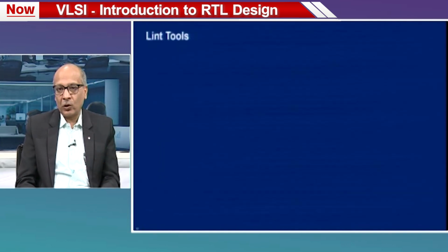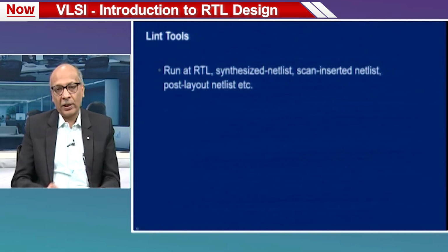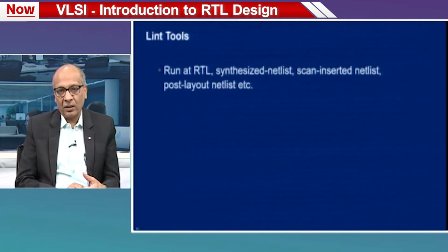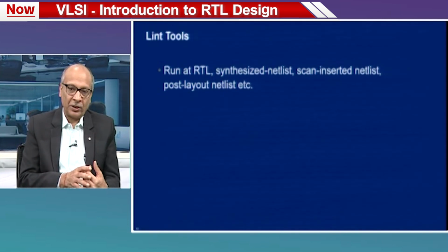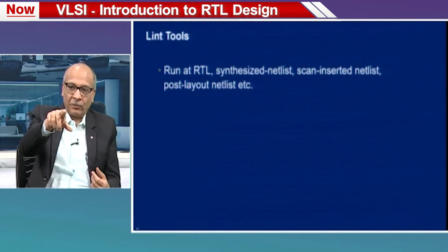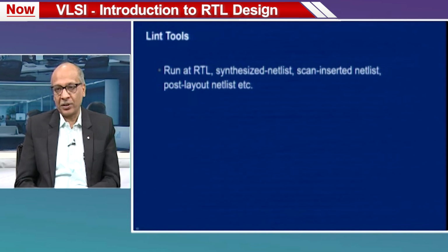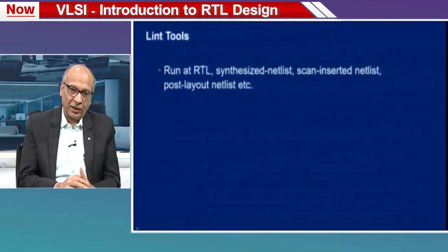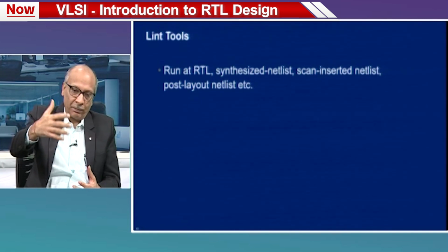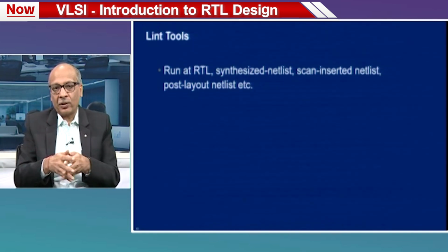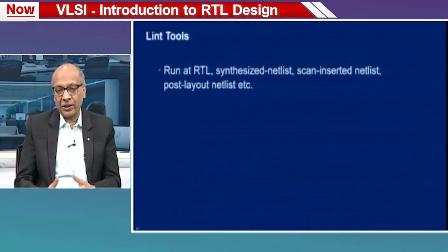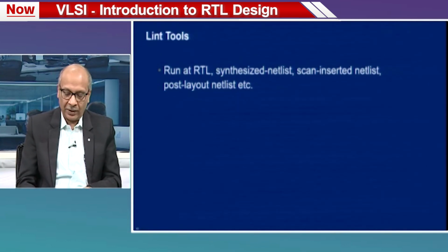Coming back to the lint tools, we can run lint tools at RTL level, at synthesized netlist level, at scan inserted netlist level, post layout netlist, etc. We will talk a little bit about what the synthesized netlist and the scan inserted netlist are slightly later. Post layout netlist we will not talk much about, but think of it as, after the design has been placed and routed, the netlist that gets created out of that, the digital connections, the gates, is called the post layout netlist after placement and routing.